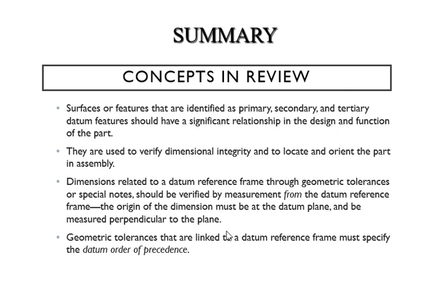And you can verify, you will measure it from the datum reference frame, of course. The origin of that dimension has to be on that datum plane because you're measuring from it. And again, all the planes are perpendicular to each other, so therefore your measurement also has to be perpendicular to these planes when you measure from it.